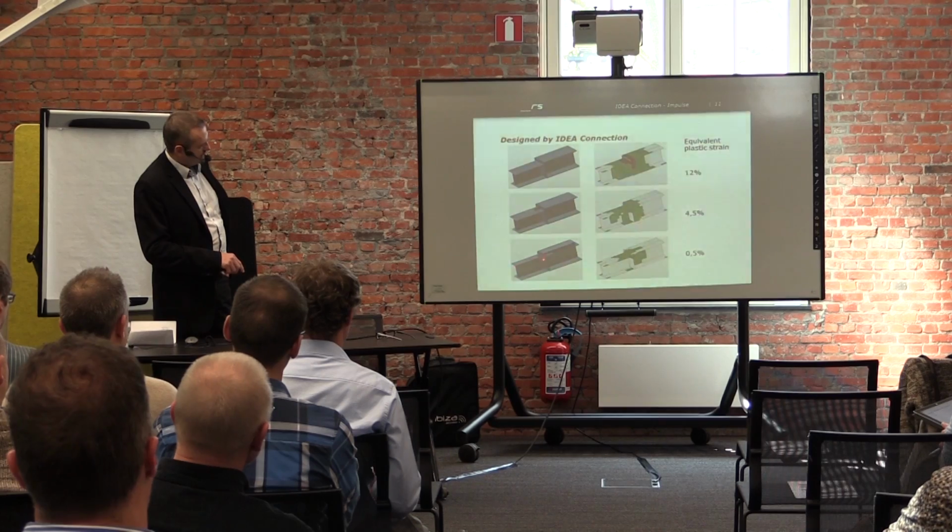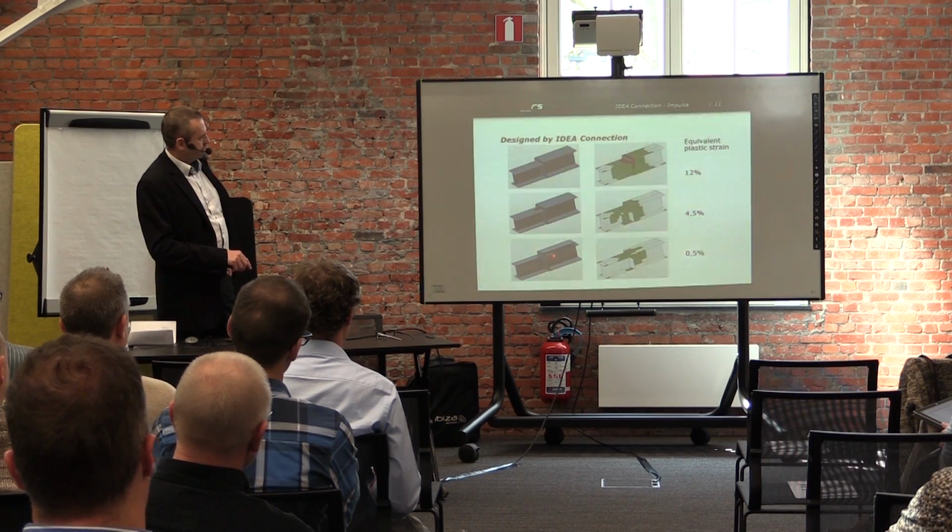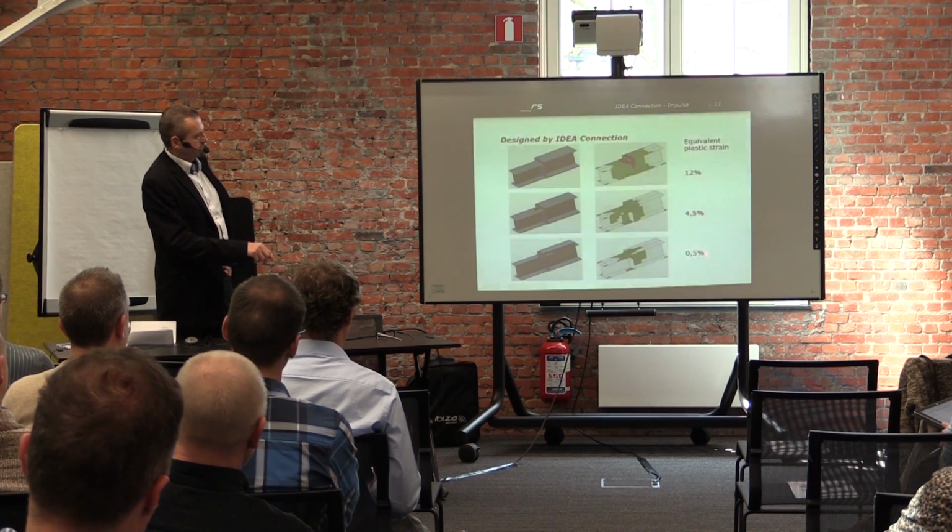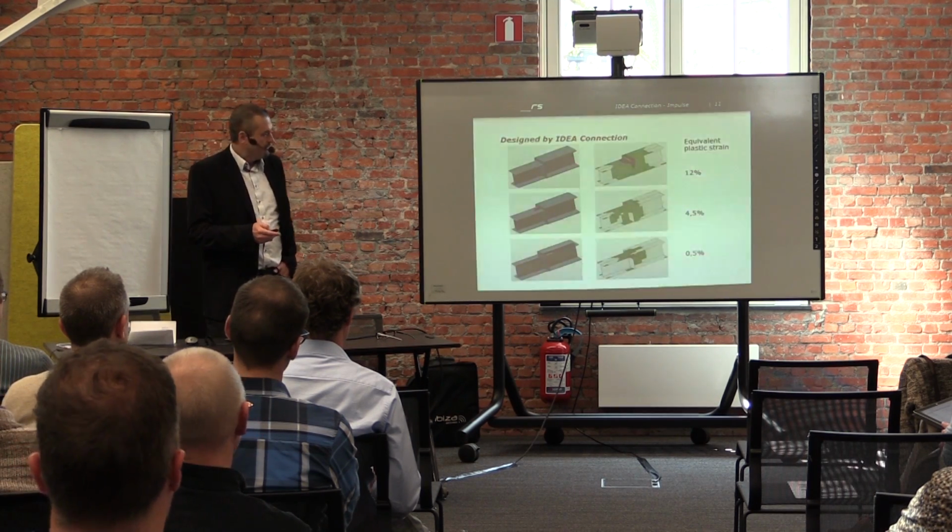Or here, I'm not sure if you see it properly, but there are stiffeners in the direction of the upper flange of this I section, and these stiffeners solve the problem very nicely. But there are a lot of different possibilities. In fact, if the designer does this analysis during his design, I think the best way is to make this plate a little bit thicker, and then it's okay.